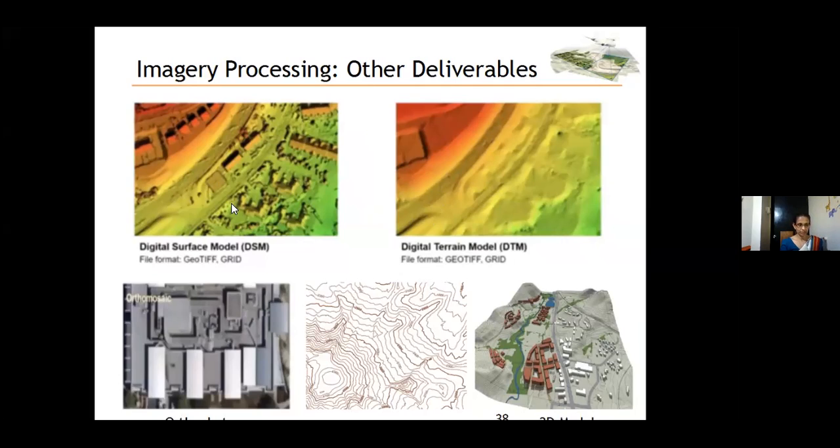In order to make good visual contrast. The next output is the orthophoto. An orthophoto is an image that has been geometrically corrected. We call this the ortho-rectification process. The ortho-rectification of each image is completed using the digital surface model that you already generated based on the dense point cloud. As this is already geometrically corrected, you can use it as a map to get measurements easily, and you have a lot of detail compared with the vector map.